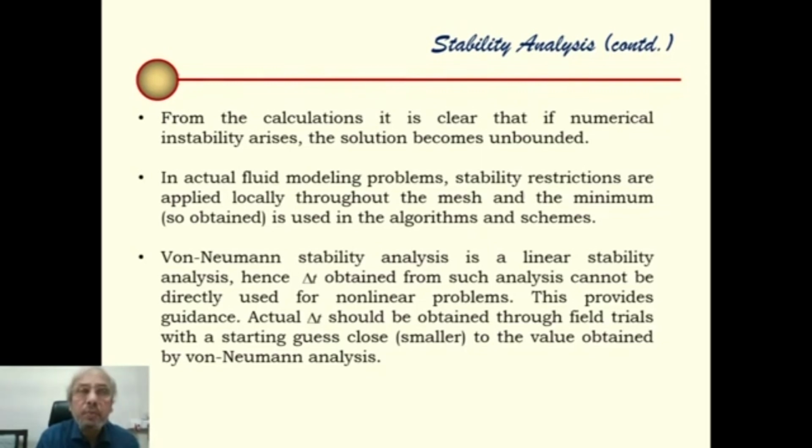And there are a few other problems also. Some heat conduction problem where transient is very important. So wherever we have to proceed through explicit formulation, stability analysis is of paramount importance. So we have to go through stability analysis to decide on the time step.